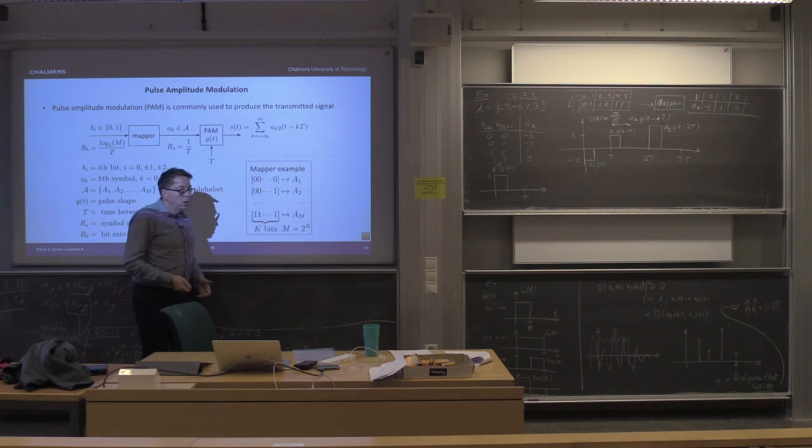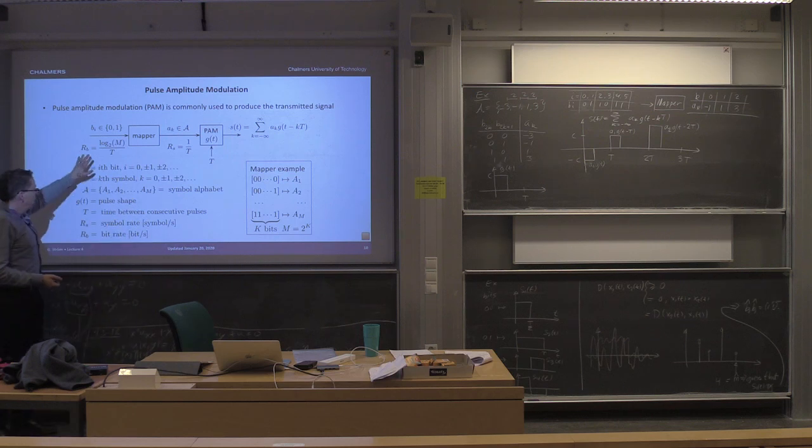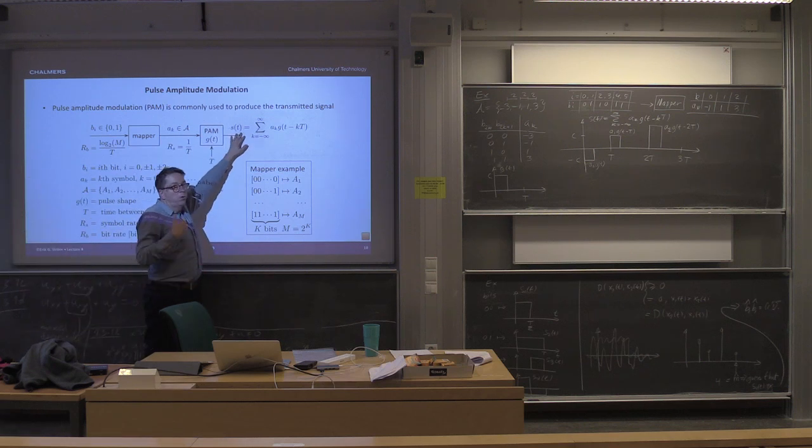So we can get high bit rate only if we have a channel where we have relatively little noise, or when we have a channel with a lot of bandwidth. Another way to turn it around is to say that if we can increase the power of the transmitted signal, we can defeat any noise we like.